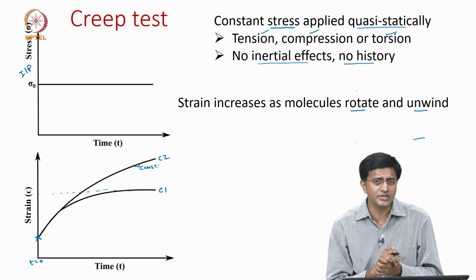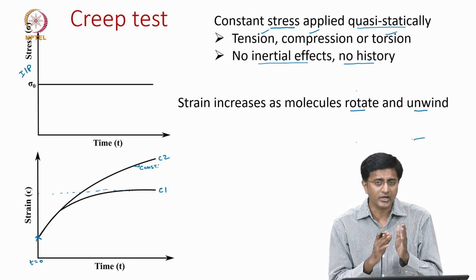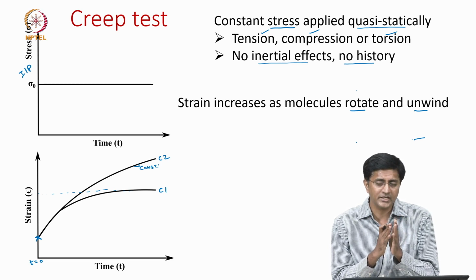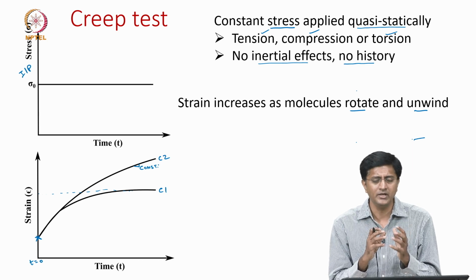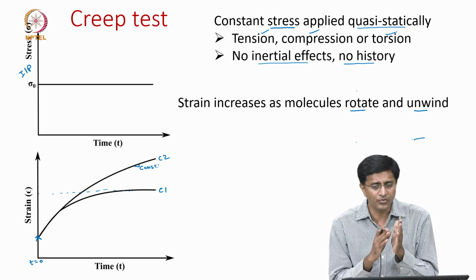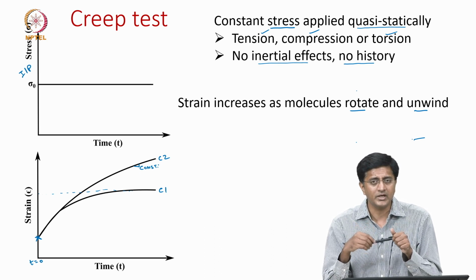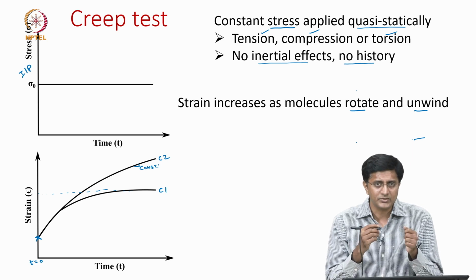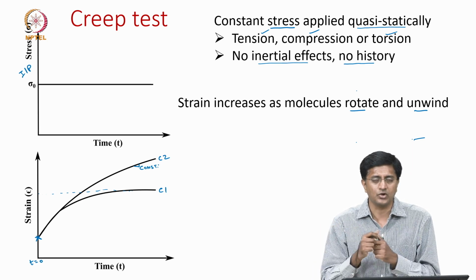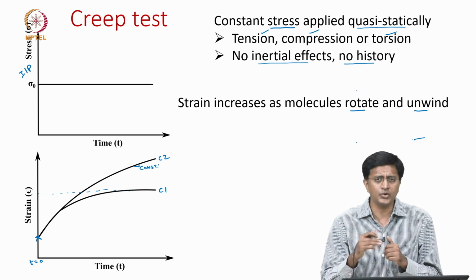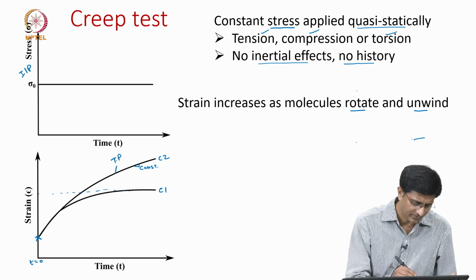So, if you think carefully, we said thermoplastics, especially if you give more time, these polymer chains slide against each other, which means if you think about it, it is more like a fluid, right. If we think about it more like a fluid and we are saying there is continuous load, how do we expect that strain to be? We expect that strain to keep on increasing. There is no reason for the strain to stop or to reach a constant value. So, this should be our thermoplast.